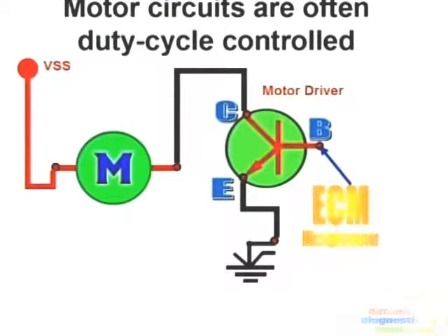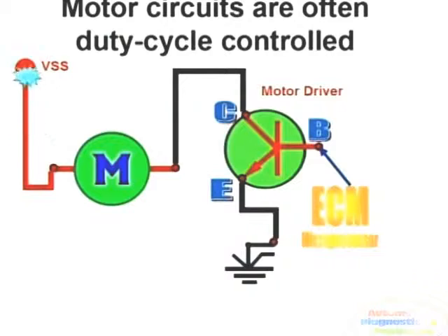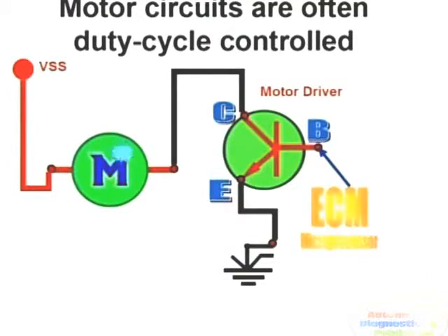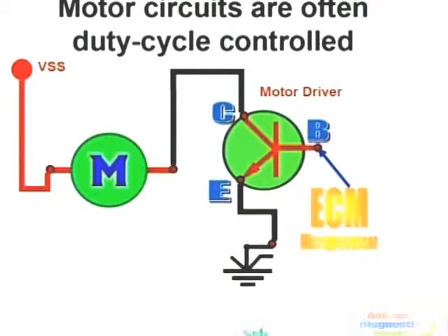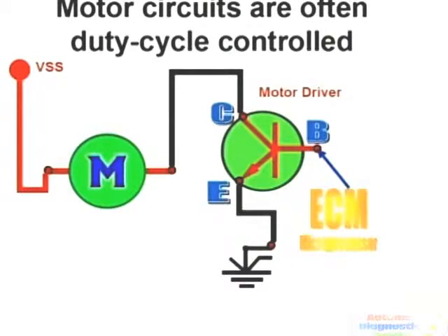In other words, without the electron flow or current, the motor would not be able to turn. And always remember that duty cycle control circuitry has to be performed by a transistor. Relays cannot be used to duty cycle control a component, since the switch rate of a mechanical relay is not fast enough for this duty cycle signal to go into effect.